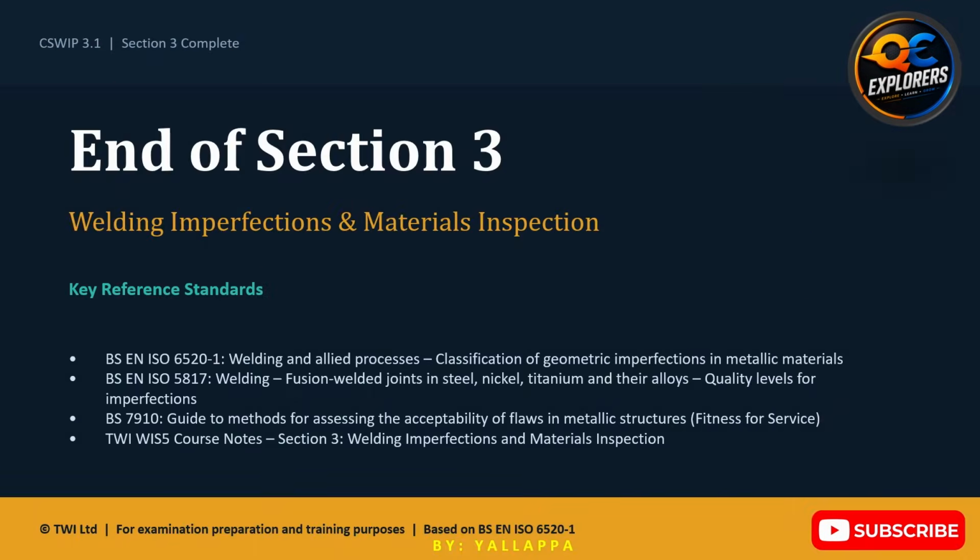That brings us to the end of Section 3, Welding Imperfections and Materials Inspection. We have covered all 6 major groups of welding imperfections identified in BS EN ISO 6520-1. We examined the mechanisms, causes, and prevention of the principal imperfections. We also considered their visual and radiographic characteristics, because inspection is not simply about knowing terminology. A competent inspector must be able to recognize what an indication represents. We then looked at acceptance standards and repair principles.